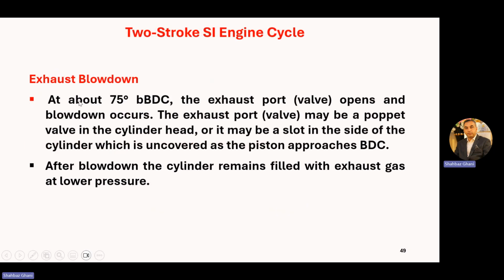Exhaust blowdown. At about 75 degrees before BDC, the exhaust ports or valves open or are uncovered and blowdown occurs. The exhaust port or valves may be a poppet valve in the cylinder head, or it may be a slot in the side of the cylinder which is uncovered as the piston approaches BDC. After blowdown, the cylinder remains filled with the exhaust gases at lower pressure.